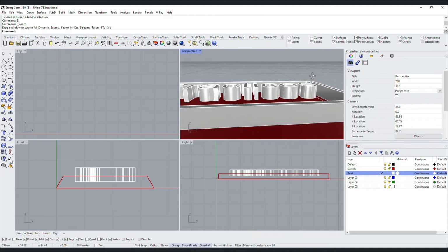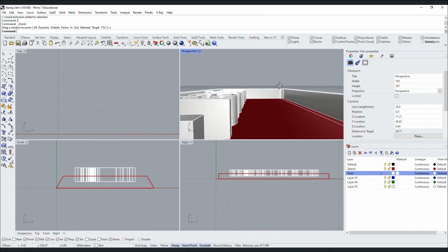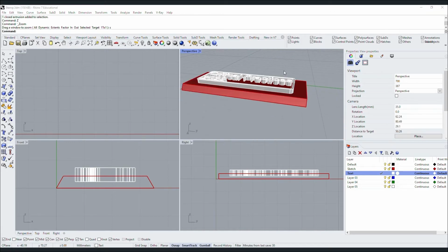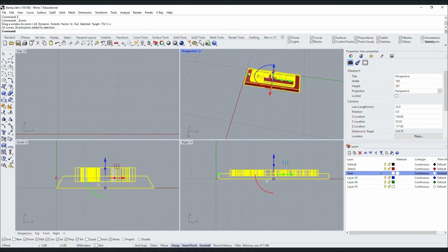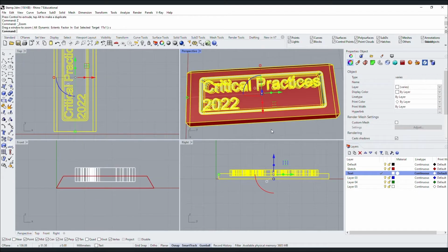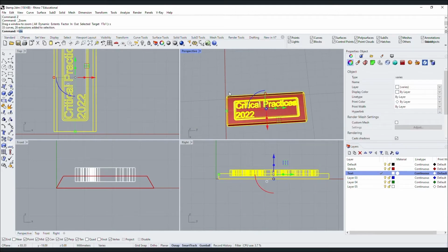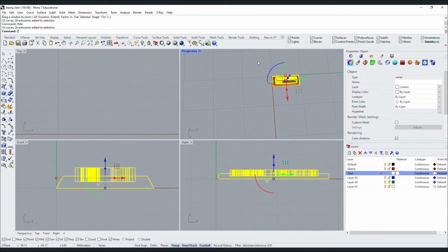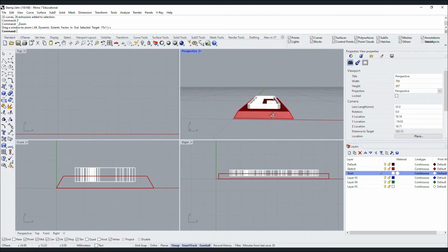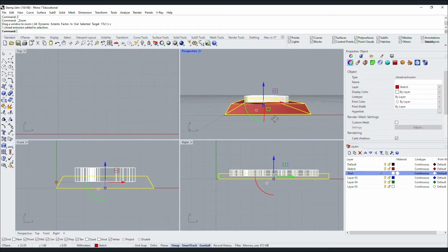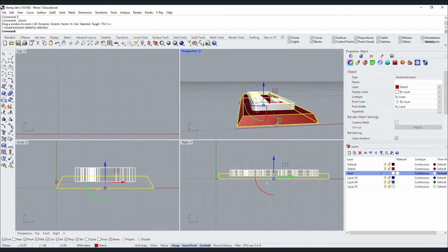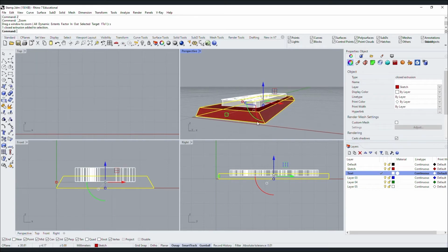And we have our basic text ready. You can also import your design from Illustrator, curves, and extrude directly. I'm just going to duplicate it by pressing Alt and dragging, and I'm going to hide it just in case for future reference. If I make any mistake, I have a copy of it in the same file. I can unhide it, or I can show it using the show command.